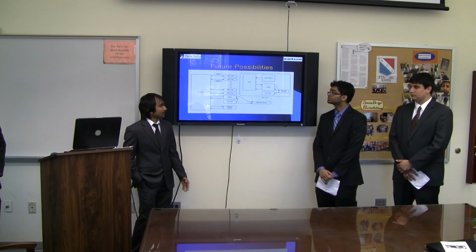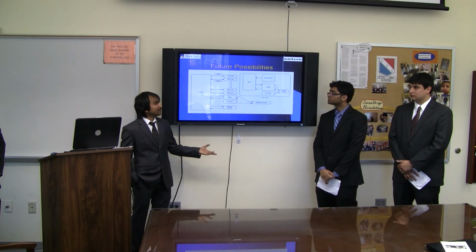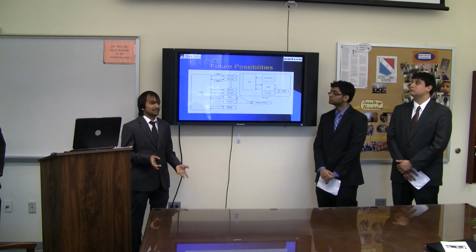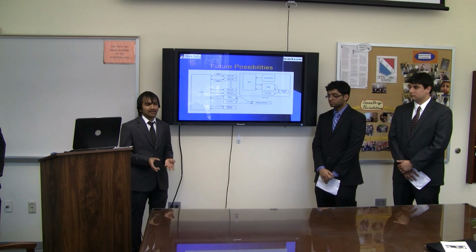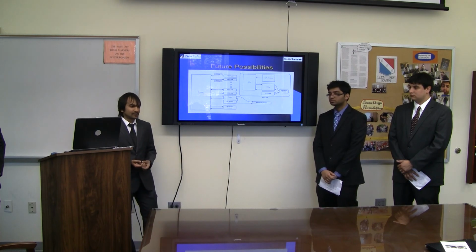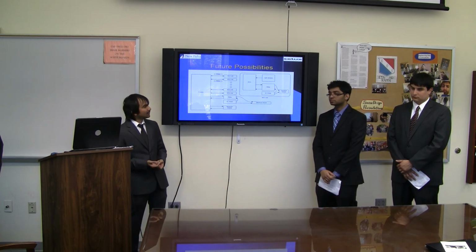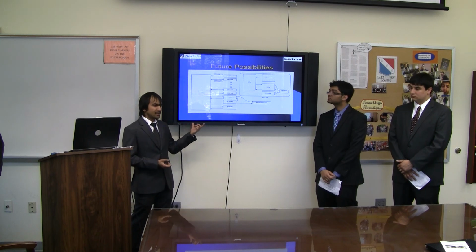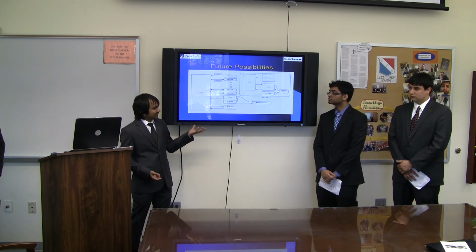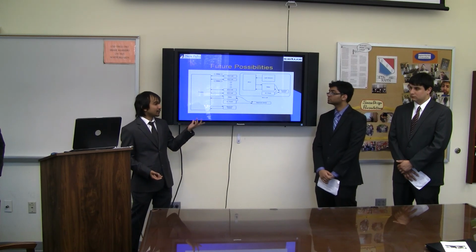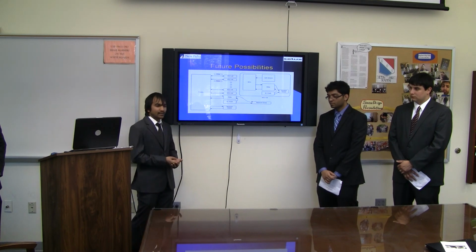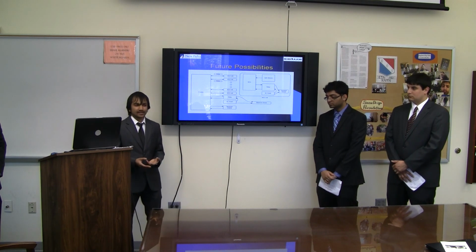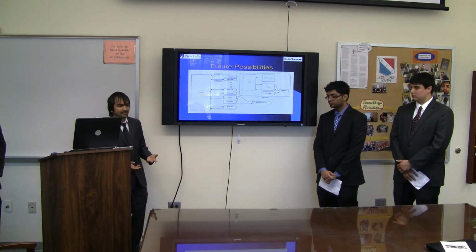Which means if we have, for example, 7 or 8 LED boards that have microcontrollers in them, we don't need 7 or 8 Bluetooth modules to communicate. We can just have one single Bluetooth module and a single extra microcontroller to communicate with all of them, which can reduce the expenses. And this microcontroller can also control any other devices that they will have inside the room, for example, lights, even a fridge or AC or any other things.